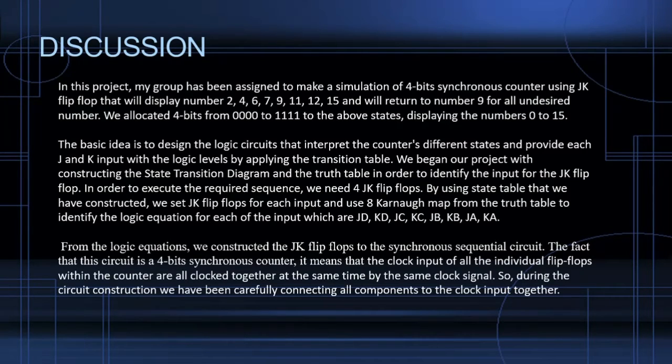The fact that this circuit is a 4-bit synchronous counter means that the clock input of all the individual flip-flops within the counter are all clocked together at the same time by the same clock signal. So during the circuit construction, we have been carefully connecting all the components to the clock input together. That's all from me. Thank you.